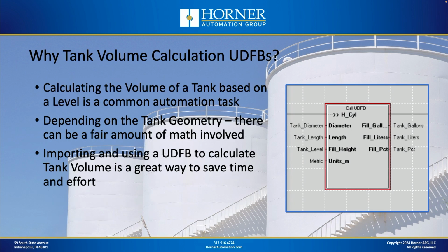Okay, so why are we creating these user-defined function blocks for the calculation of tank volume, other than the fact that a customer requested it? Well, it's a common task to measure the level in a tank and then calculate the volume, whether it's in gallons or liters or cubic meters or whatever the case may be. However, based on the geometry of some tanks, it involves a fair amount of math to make that calculation. So we thought we would make it easy on you by providing these user-defined function blocks.